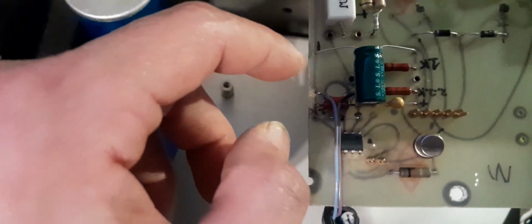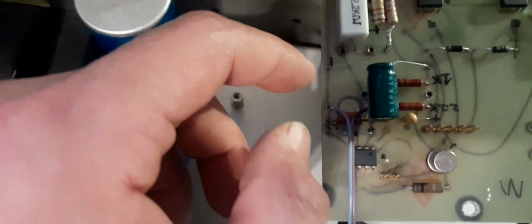That way I can minimize the inductance on the leads going to it, because it's probably getting its power supply from something here that's smoothed by a cap, and then there's inductance going to that, and then it's doing its own regulation with a cap in there that could cause a seesaw effect. And for oscillation reasons, with it going into the input of an op amp, it's also better to have it as close as possible.